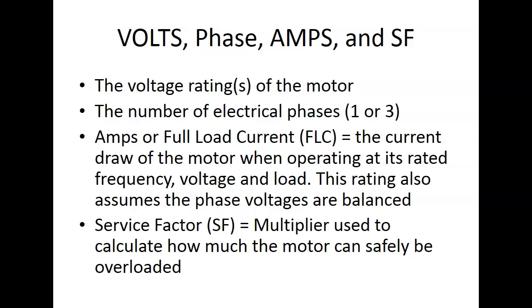Well, no, it's how much you can safely overload the motor. So ours has a service factor of 1. My motor, the black motor, has a service factor of 1.15. If you're running at 208, it's got a service factor of 1. So that's how much we can safely overload the motor, right? Not for extended periods of time, but for brief periods of time, right?